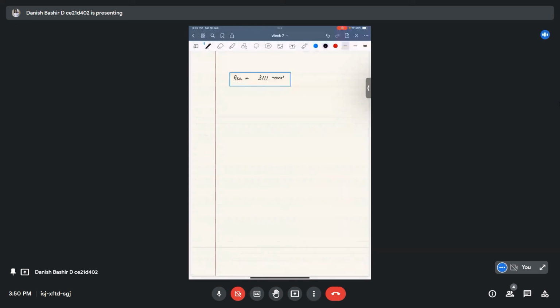We have to distribute this Asc in longitudinal reinforcement, keeping in mind the section of the column as well. Since our column is longer in one direction and shorter in the other, we will first place 4 longitudinal bars at the 4 corners, and then arrange the remaining area with bars at intermediate positions between the corner bars.